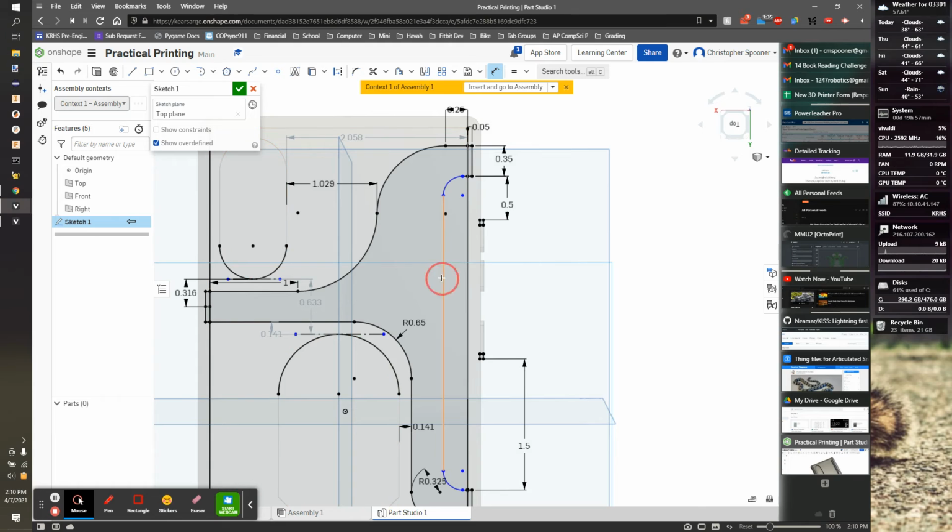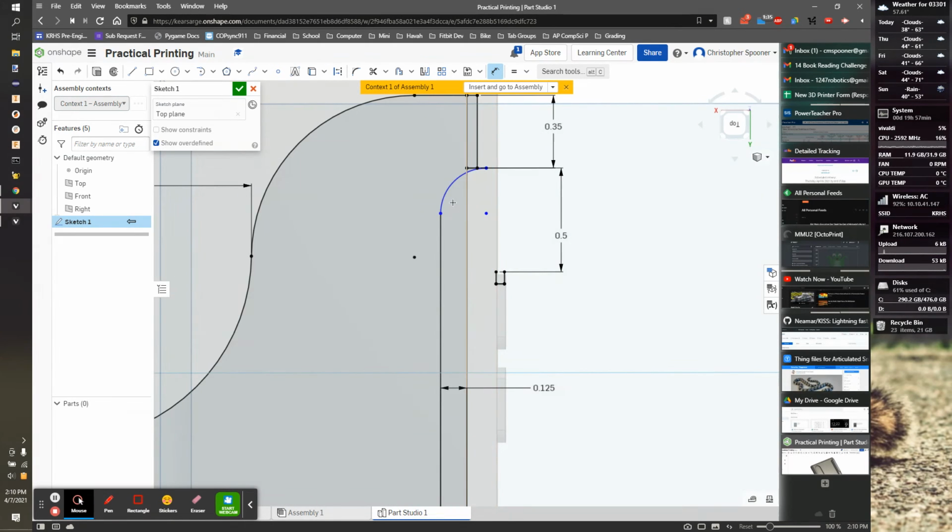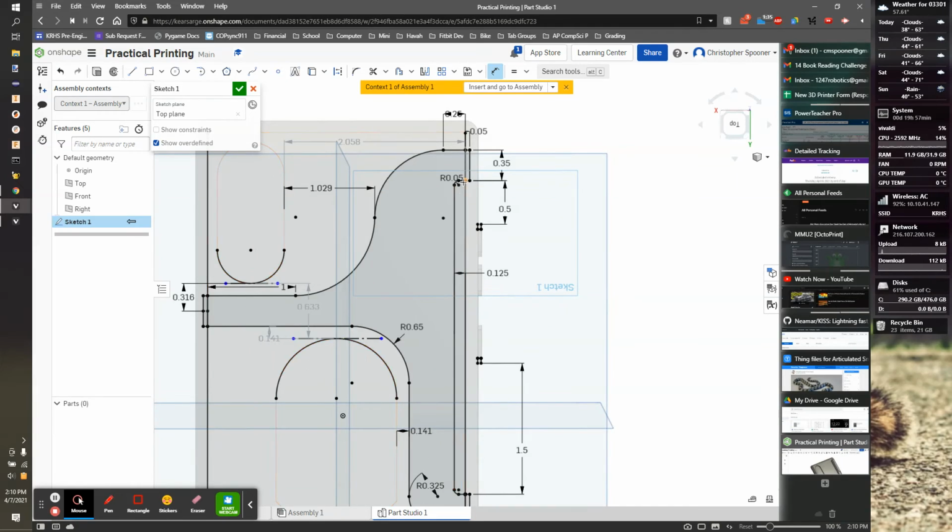And let's give ourselves some dimension from here to the wall. So let's make some dimension. Let's do 0.125. That's an eighth of an inch. Okay. Now I still have to fix these guys. So I'm going to bring those corners inwards. I'm going to pick a value for this number. Let's do 0.05. Okay. So now I'm going to take and extrude this 0.05.